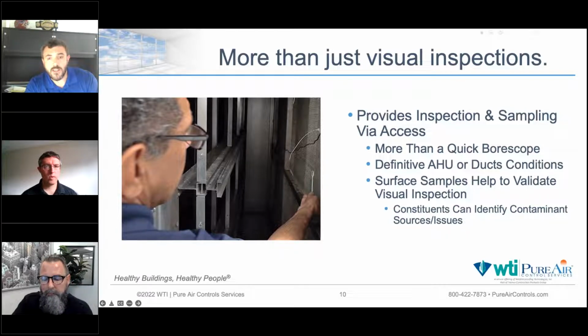There's interesting data when you get into things like, what's the RPM of the unit running at? And you compare that RPM to what it was designed to run at. And if it's not running at design, there might be some issue. You know, we might want to make some changes.